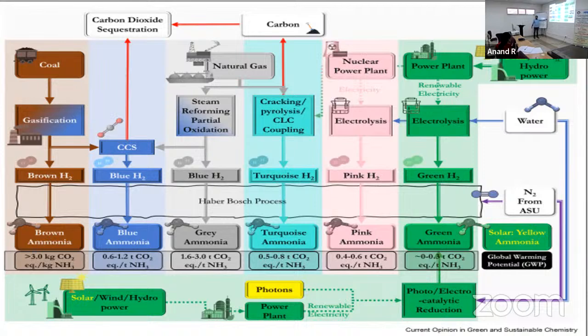3 kg CO2 equivalent per kg of ammonia product. Similarly, you have to calculate. This is only global warming potential. Life cycle assessment does not only have global warming potential. As I already listed in the PPT, there are so many things: acidification, human toxicity, everything is there. Based on what you need, you can take. If you only consider global warming potential, then that alone is sufficient. If you consider 2 or 3 parameters combined, then you have to take them.